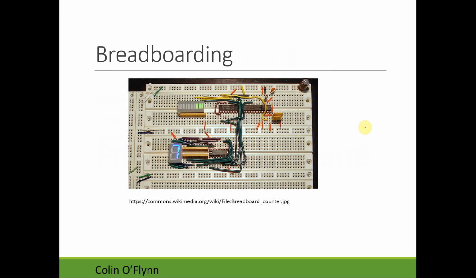All right, so printed circuit boards. They are sort of the progression when we're doing electronics design. The most basic thing we can do is breadboarding. So you've already used breadboards, and here we have the chips that are connected through these temporary wires to form the electrical connections. And this is fine, but there's a few issues with it. Number one is reliability. If you're trying to mount this somewhere that's going to vibrate, these wires could fall out. They could just be knocked out. You can get oxidation on the contacts.